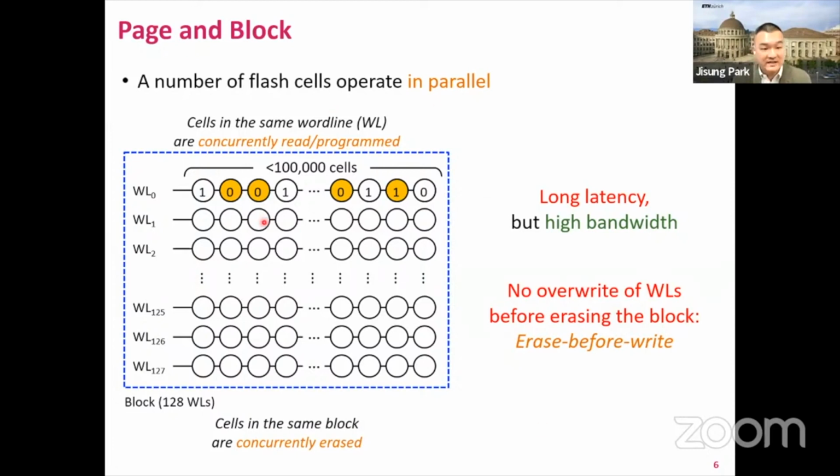For example, the second cell in the word line, making this cell a 1 cell requires decreasing the cell threshold voltage level. But as we discussed, the program operation can only increase the target cell's threshold voltage level. So to update the second cell in this case to store bit data 1, we need to erase the cell, which requires erasing all the cells in the block.